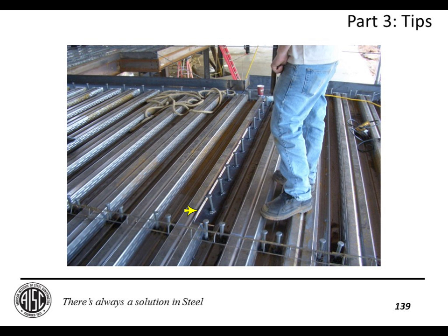I have seen them just drill holes in the top of the high flute and try to shoot studs down through those holes. That is absolutely not what we want to have happen. Probably the best case scenario here would have been for us to design this beam as non-composite so that we didn't have to worry about this issue to begin with.